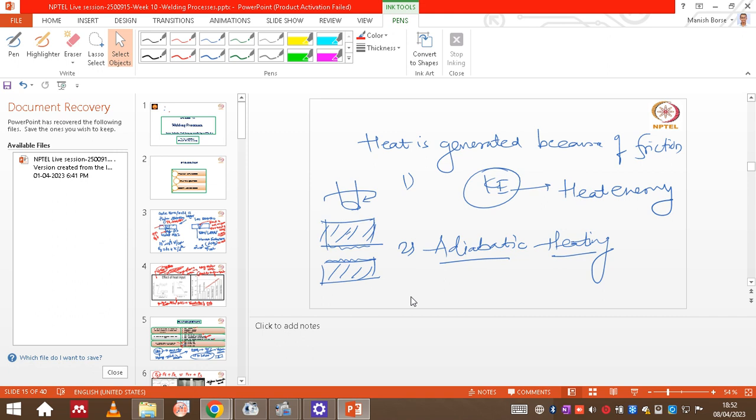Heat reflectivity means you mean to say in friction stir welding? No, it won't have any problem in friction welding, because though the thermal conductivity is higher, sigma y of the aluminum is softened very easily, like even at 200 degrees Celsius for precipitation alloy.